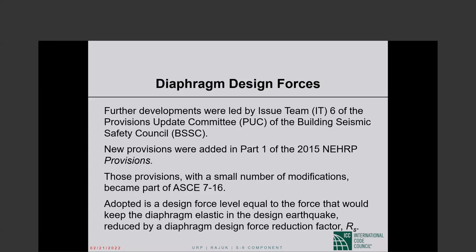So, how to design a podium slab to resist huge lateral loads? They are sometimes feet thick. Feet. If it is a tall tower sitting on a podium, you can have a 5 foot thick slab acting as the transfer diaphragm. So the design is no different from that of other slabs, but you have a lot of shear in the diaphragm, and even with reinforcement, you need a lot of thickness.